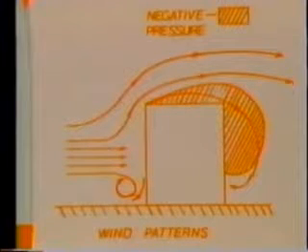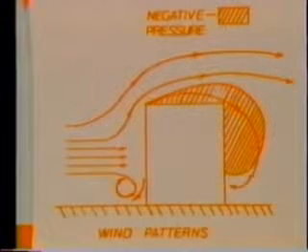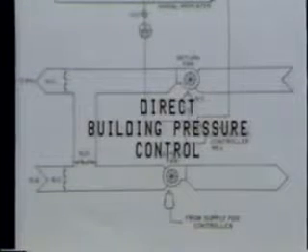Obtaining a stable atmospheric reference is often difficult. It depends on building shape, size, location, and wind patterns around the building. However, the effort is very rewarding when one considers how simple the control system would be. Control supply fans from a point in the duct which permits least energy use at the fan, and control the return fan capacity to maintain building static.